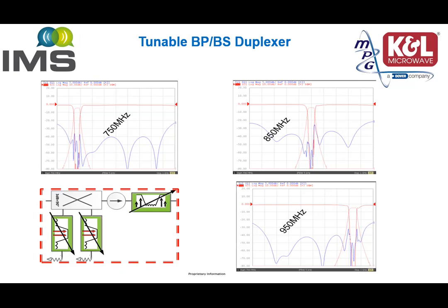They will come out of phase at port 1 and in phase at port 4, which enables them to continue and travel through the isolator into the tunable band reject filter. In short, we are getting a two-port device that acts as a tunable bandpass bandstop.